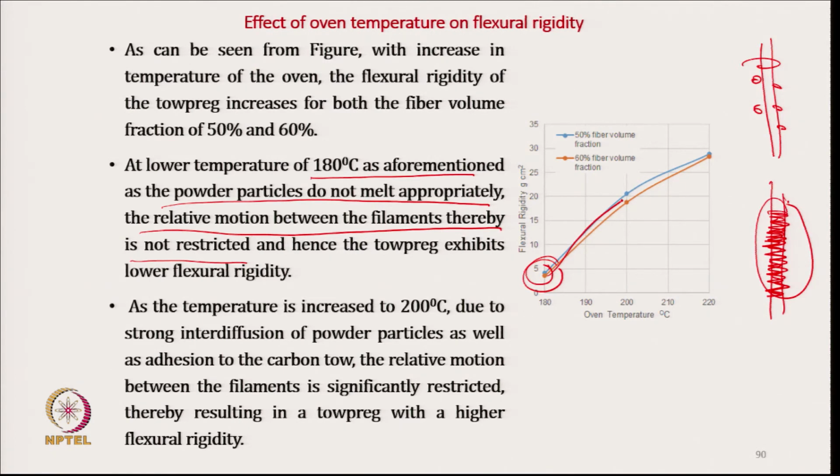It further increases as the temperature goes up to 220 degree Celsius, because at that stage, in addition to the surface melting, the polypropylene matrix penetrates inside the carbon toe. So, that helps in enhancing the flexural rigidity.